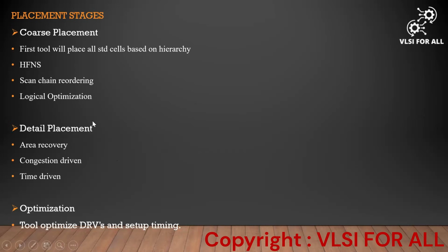Placement stages. In placement, it will be done in different stages. One is coarse placement, another is detailed placement, and another is optimization. In coarse placement, again, there are some steps. First, the tool will place all the standard cells roughly